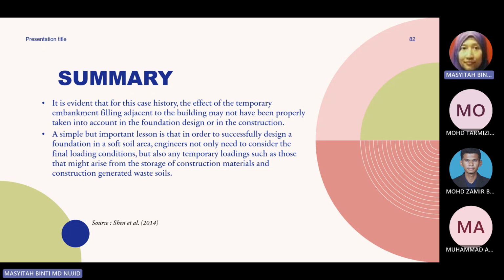So for this problem, something that cannot be captured by hand calculation or approximate methods comes to numerical simulation. But the problem with numerical simulations is that not everyone understands how to use the software, right? Getting the soil parameters and interpreting them into the software, not everyone can understand whether the parameters are suitable. Also, for example, PLAXIS has method A, method B, method C. Method A is, for example, undrained, then method B is drained, but drained and undrained here represent different strength parameters of soil.